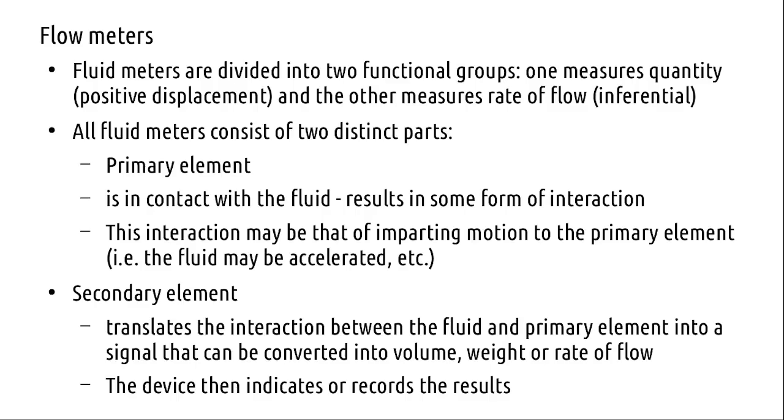Okay, coming to flow meters. Flow meters you can divide into 2 groups. One type of meters measure quantity. That's called a positive displacement type of flow meters. The other measures rate of flow, or you call them inferential type of flow meters.